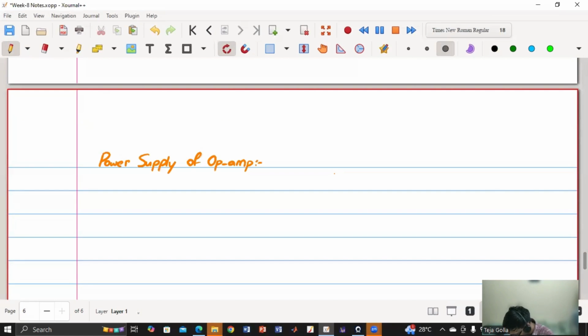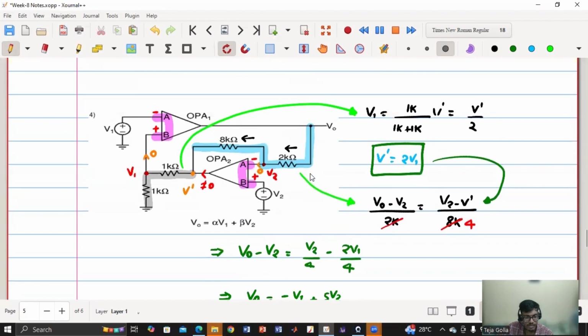Okay, at this time, negative feedback, meaning you cannot actually understand because you need to know some controls background. Then only you can actually understand. Negative feedback is something like this. You can think in a way: say I need my output voltage to be at some point. So what my circuit does is, if my output voltage is not regulated, with a negative feedback mechanism, if the output is going down, my circuit will make it increase. If my output is increasing, my circuit will make it go down, right?